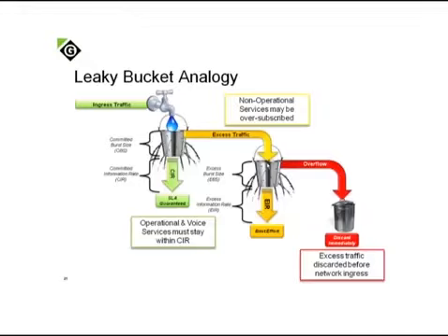So your newer routers and switches, mostly routers, in your substations, they're hardened routers, have what's known as traffic policing. And so it's constantly monitoring the traffic and saying, is it a green frame? Is it a yellow frame? Hey, it's outside of both bounds, throw it away. Don't even let it get into the network. So that's the reason why we use the leaky bucket analogy, because if you think about it that way, it's easy to see where in the path things get thrown away.